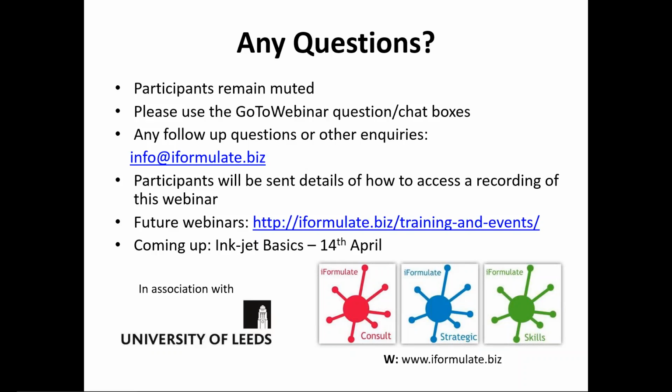Now that obviously refers to the food and chemical industry. If you're talking about the pharma industry, where you're only trying to produce a number of kilos per day or per week, then that's less important. It is one of the most cost-effective ways, though, of drying, and particularly on a large scale. It's also very efficient. As you can imagine, you can get over 100 tons per hour through a spray drying tower. So you're talking of probably less than $1 a kilo of product, but all that depends on how easy it is to dry and how much moisture there is in the system.